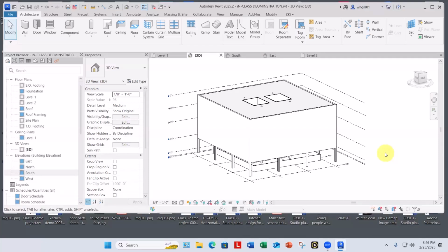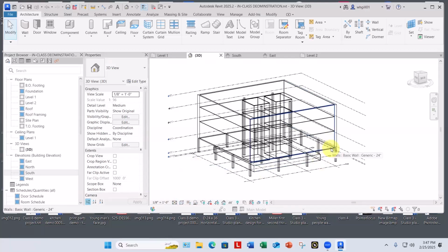So that's all any of us have the energy and time for. I know this has been kind of a painful day, but what we've done is get an accurate base plan into our Revit model. We've got grids, we have the center lines, we can mirror things around, because so much that happens on the left side of the building happens on the right side as well, from top to bottom, north to south. We've extended some things from the ground all the way through the roof. We've copied things. And we don't have to say copy this up 37.6. We just say copy it from this level to this level to this level. And then when we move those levels, the floors will go through.